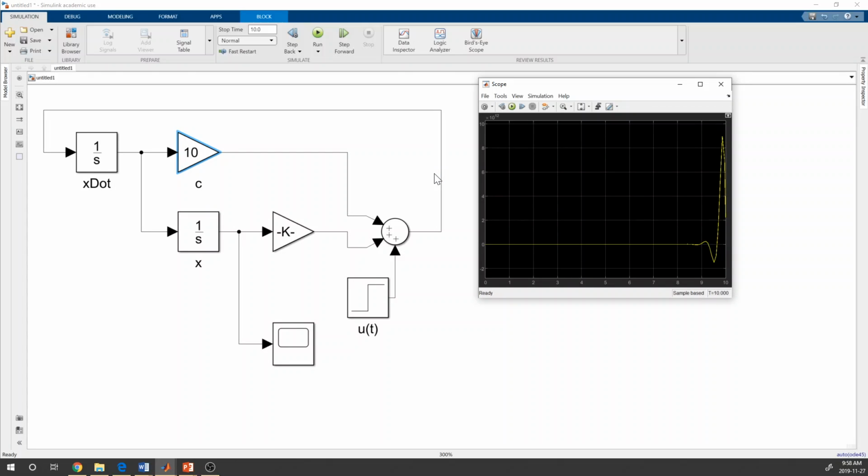And we'll see here, my computer happens to be really good at dealing with instability. So it looks like there's almost nothing happening, and then we get this massive spike. But look at my numbers here. I have 10 times 10 to the power of 12, indicating that I have an instability condition. So that's what that'll look like. On some computers, or if you run it for long enough, what you'll see is that it'll come up with an error and say, hey, this is infinite, what do I do? Anything like that. So if you have an unstable system, that is what you're going to see.